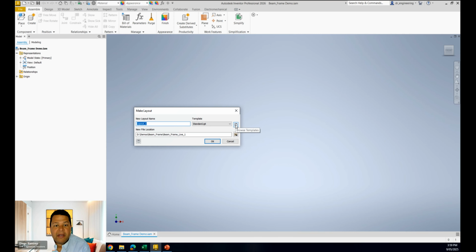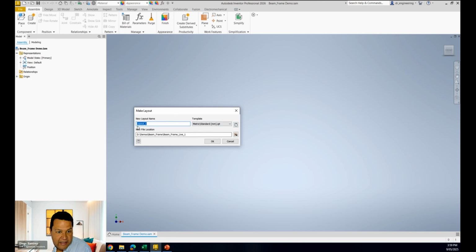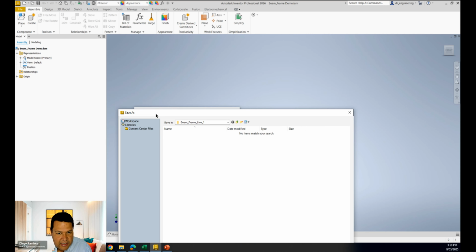That's the first step. In frame generator, basically we're gonna have the different structural members, and they're gonna be represented by the center line. So all of the center lines can be made using sketches, and they're gonna be the base to create this type of model. So we're going to metric. Let's give it a name in here. This one, and that's gonna be the number 2, and you can change the folder to this one from here. So that's all.